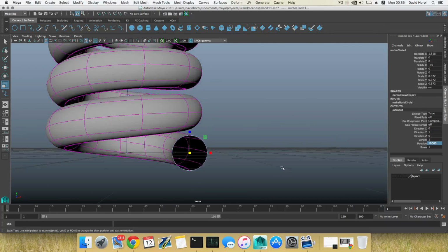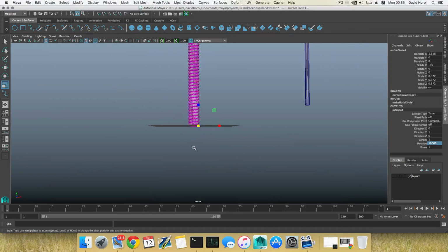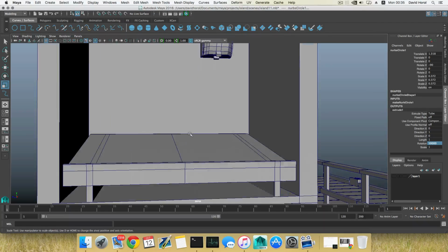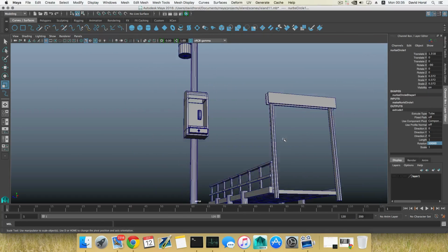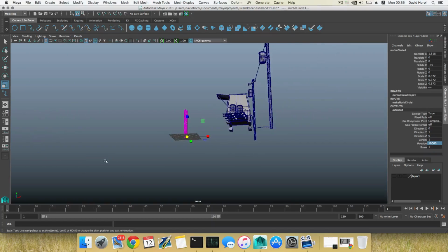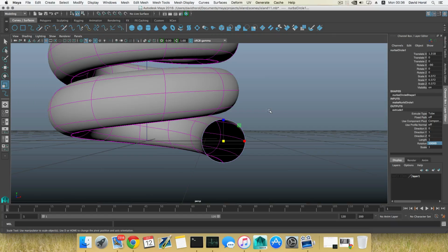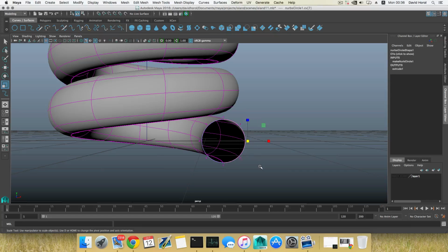Now, if you want, and yeah, I suggest you will, and the reason is because earlier we added those in the phone, we added these 2 slots here or whatever just to assemble the cord into them. So there are like cubic ones, and because of that, what I will do here, and he basically did it also in his own video tutorial, you're gonna right click, choose Control Vertices, you can grab these 3 here, and shift select these 3. Sorry, I haven't clicked on shift.